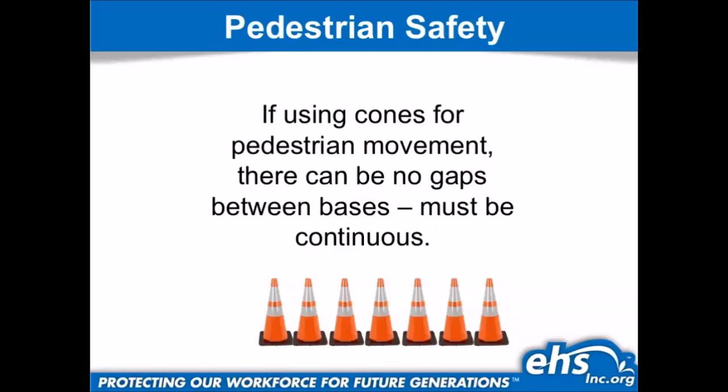Now, if you're guiding traffic on sidewalks and you're using cones, so you're providing a path for them or you're closing off access to sidewalks, if using cones for pedestrian movement, there can be no gaps between bases. It must be continuous. So what this standard literally says is, hey, if you're using cones to close off a sidewalk or provide a path for pedestrians, all of the cones have to be butted together end to end. And some people think that this is written by the state to kind of keep people from climbing over the cones and walking through the area.